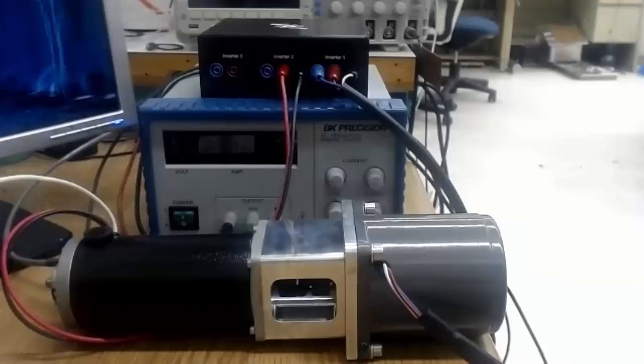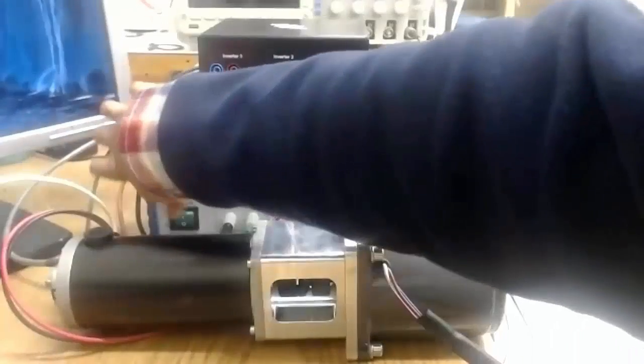Here's the setup that we are going to be using for this example. It is very similar to the one that we used for the DC motor speed control. It has the same inverter module and the DC generator to generate the load torque. The only thing that has changed is instead of using a DC motor, we are going to be using an induction motor. So the motor on the right is a three-phase induction motor that has a rating of 24 volts line-to-line RMS, a rated frequency of 60 Hz, and a rated current of 2.8 ampere peak. The induction motor is going to be under speed control, and the coupled DC generator is going to emulate a load torque. So let's go ahead and run this example.